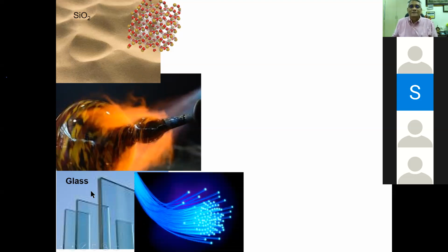Okay. But glass has various applications, the non-crystalline form of silicon dioxide. So when I said materials obtained in amorphous form, it doesn't mean that they're not good for applications. The fiber optic communication technology is all based on silicon dioxide coated fibers. You need to get that total internal reflection, and the glassy form of silicon dioxide helps in maintaining the flexibility. If you have a crystalline silicon dioxide coated inside these flexible fibers, they'll break, they'll chip off, right? So the glassy form helps there.